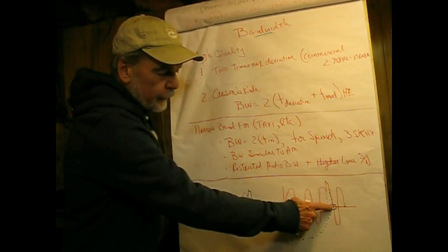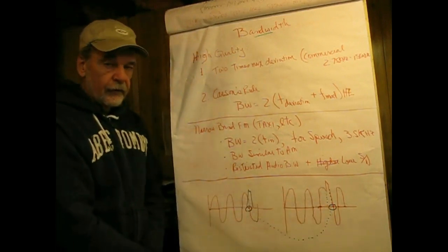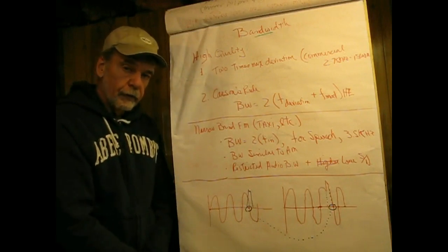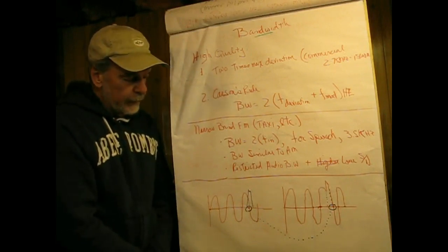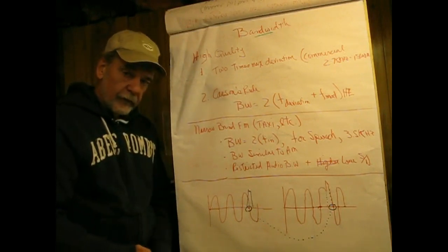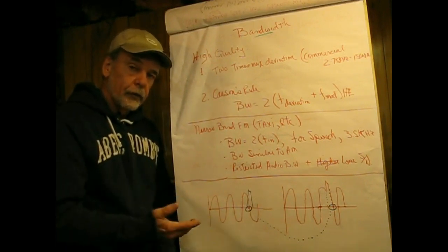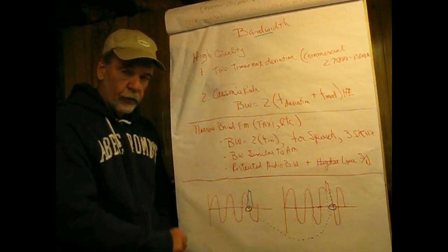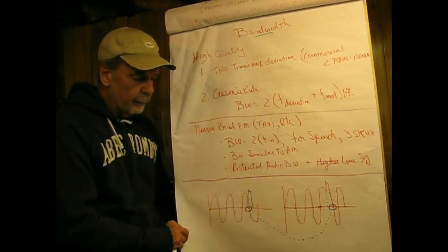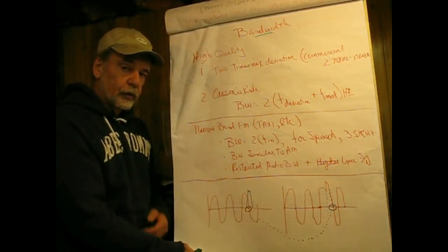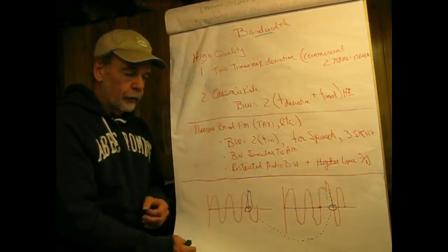This basically means that the phase is shifted, and what we know is that frequency is a function of phase change. So we cannot say that an FM transmission system is completely immune to noise caused by man-made sources or atmospherics or anything like that. There is a bit of phase modulation which occurs, which will decrease the signal-to-noise ratio.